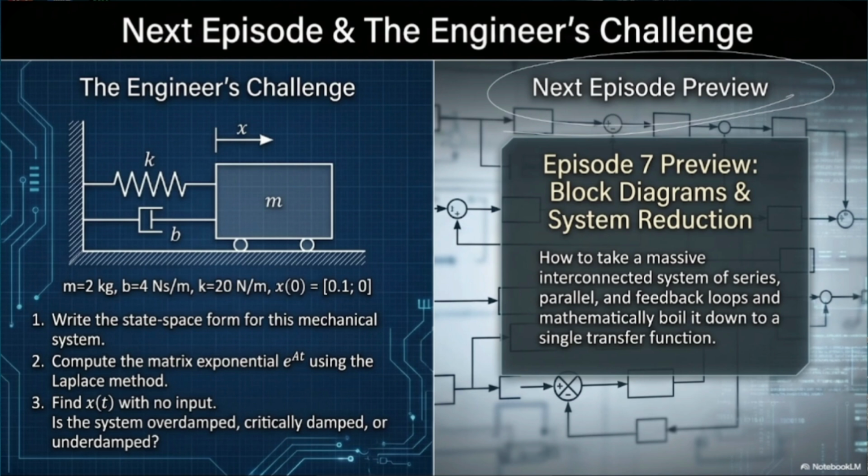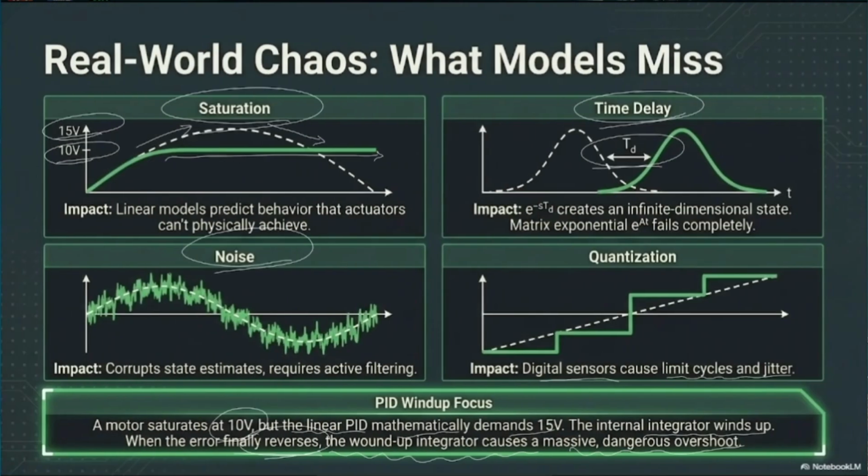We use two rules of thumb for that: either you need accuracy or stability of the system. And at the end of the day, we consider the limitation of your physical model. It means that if everything goes well in the simulation, it doesn't necessarily mean that your simulation is going to be implemented exactly in your actual system. Your actual system is going to have limitations, and as you saw before, we have saturation, time delay, noise, and quantization that you have to be very careful about.